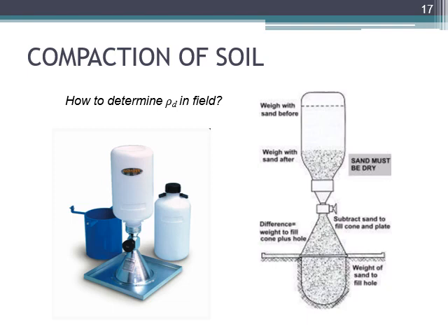If we already know the water content of the soil layer, then what is left to be determined is the bulk density. Bulk density, so the mass of the sample and the volume of the sample. So of course we can dig a hole, right, and take the sample from the hole and measure its mass. It is not a problem. The problem is how to determine the volume of that sample, because if you take it to some plastic bag, then of course the volume of it is different than the volume of the soil in the ground.